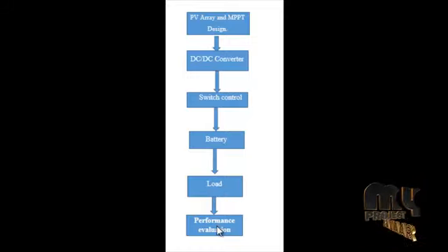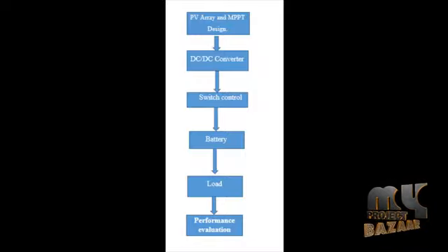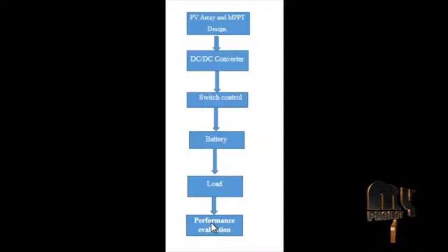Next, we calculate the performance evaluation. We run the simulation for both sunny and cloudy day scenarios, with input temperature and irradiance data for both of the load cases mentioned, giving a total of 24-hour simulation. We simulate the following cases: sunny day conditions with constant load resistance, and cloudy conditions with constant load resistance. For each simulation we will use 14401 one-minute time steps.